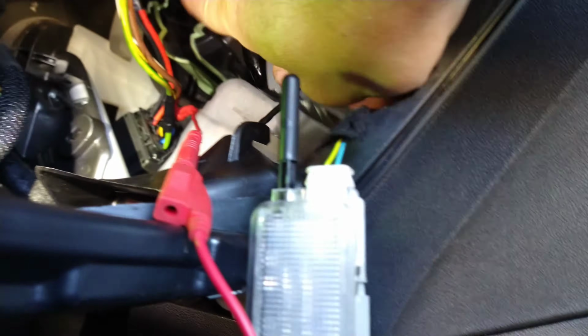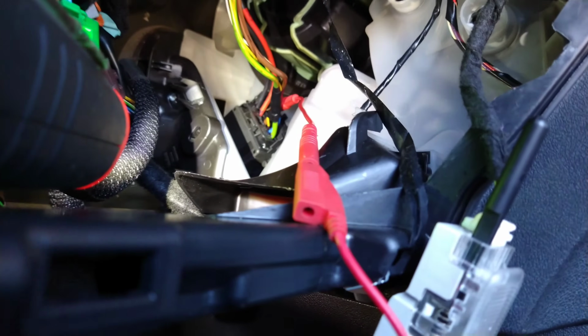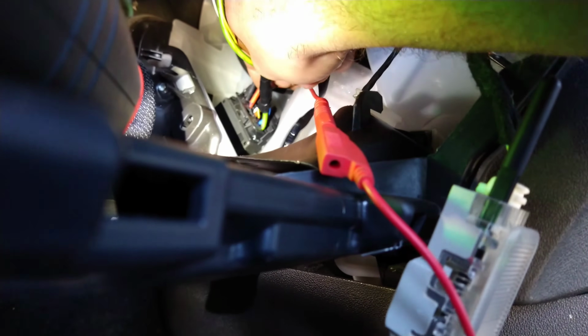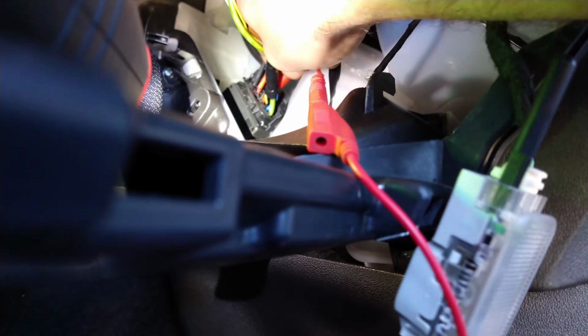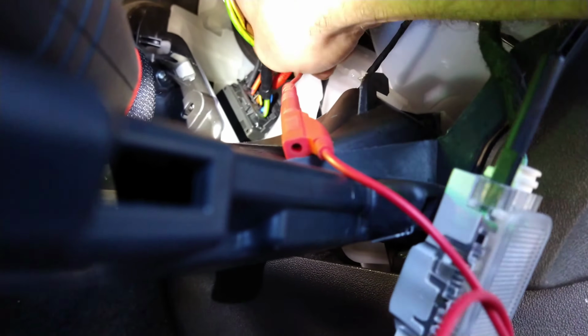The next one down is also 12 volts. So those two wires, the black and the red, go to the blower motor just above it, up there. So it'll control the ground, almost like having something in series to control the ground. And that way, it'll control the blower speed.